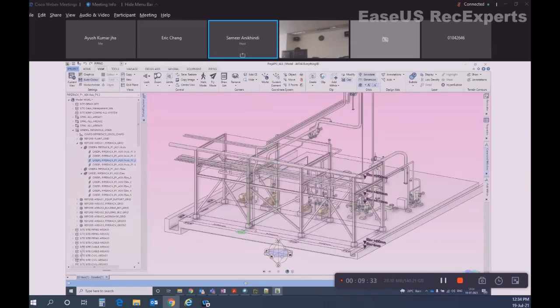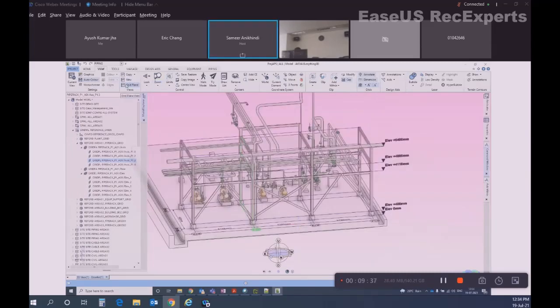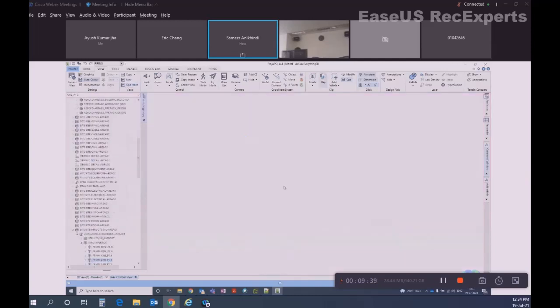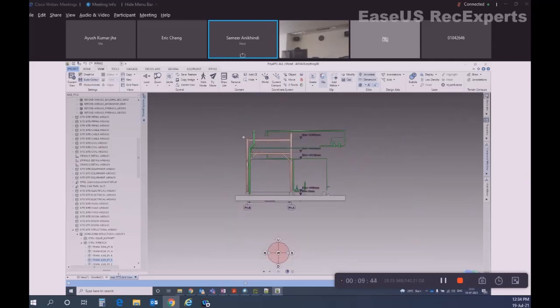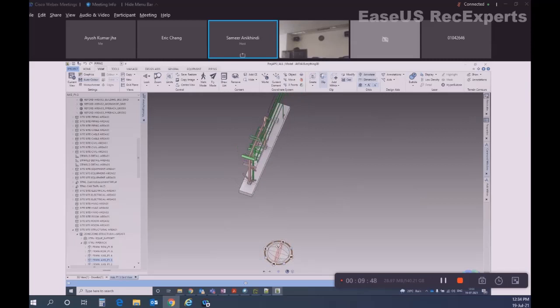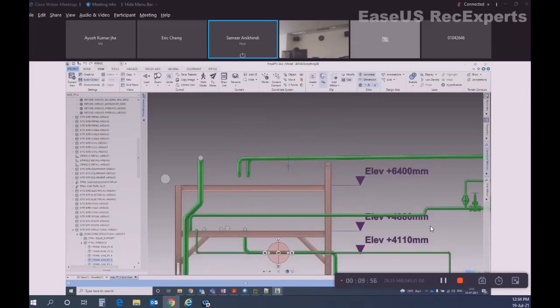Once you select one individual plane, you can go to grid plane view and it will clip this grid plane. You can see it makes another view, access P13 grid view, and it's a clipped view actually. It will clip 100 mm in front and 100 mm in the back, and you can visualize it.